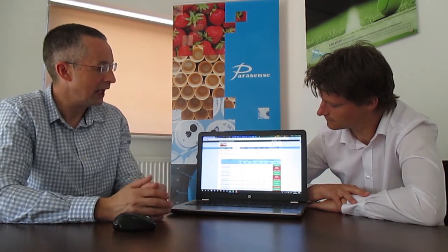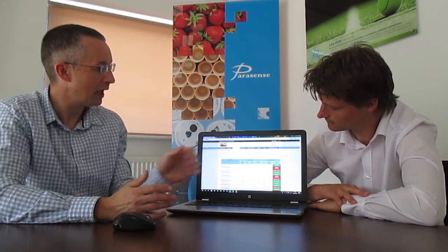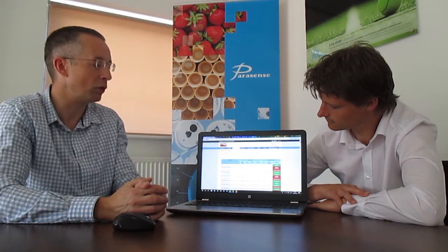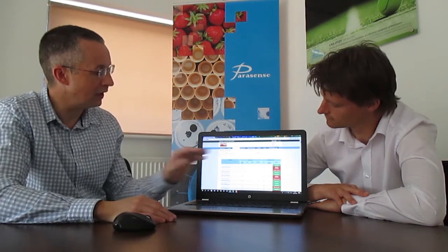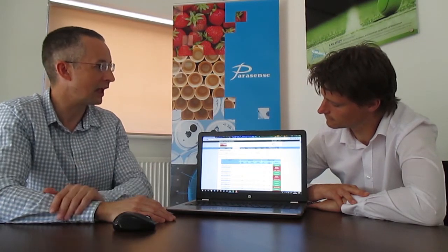So the alert, alarm and critical is working around that theory. So the alert is ppm values really from as low as 1 ppm up to around 40 to 50 ppm. The alarm levels are anything from 40 up to 200 ppm, and the critical are really the high level leaks, so that's anything from 500 ppm or greater. They could be your catastrophic leaks, etc. So it allows us to really look down at the small leaks, the ones that are leaking all the time, that are contributing to that leakage rate, and if we can capture those, we can hopefully reduce your refrigerant usage by capturing those early before they move into the alarm and critical state.